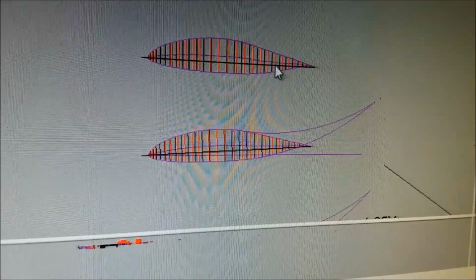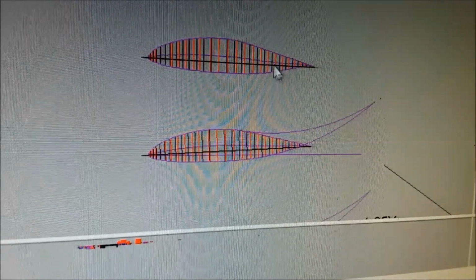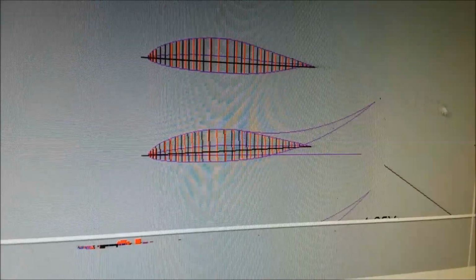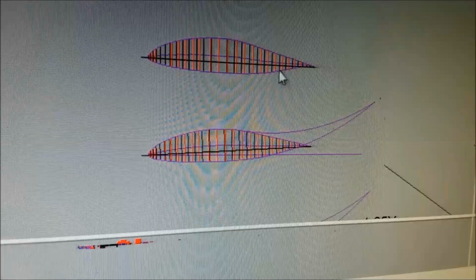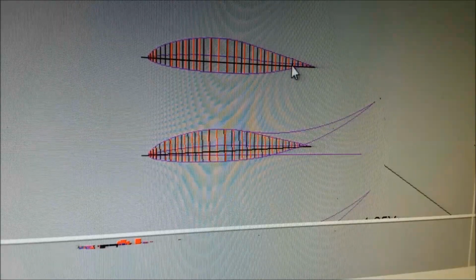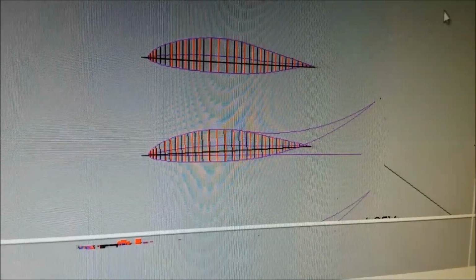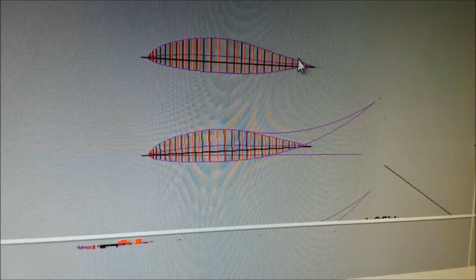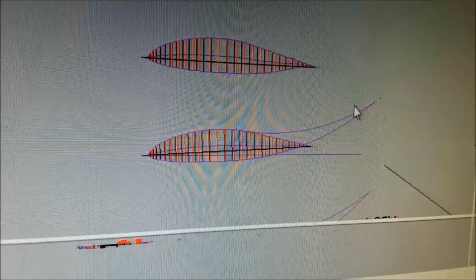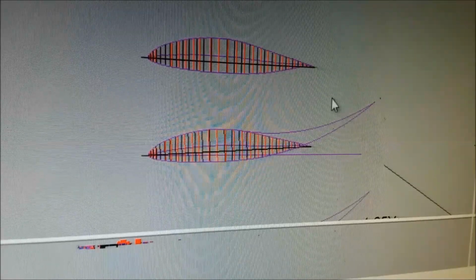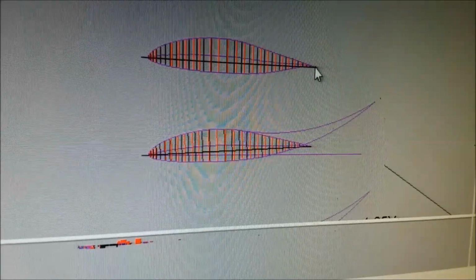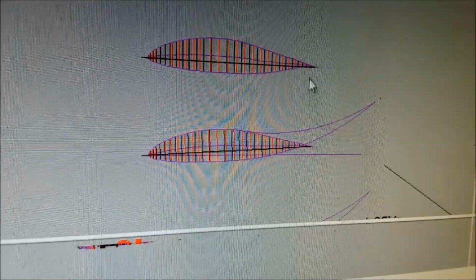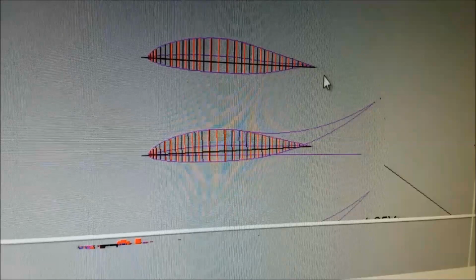If you have a Cessna Piper Cub kind of thing, the tailplane is down, but the wing is so high it never deflects the air down to it. But if you have a low wing plane, like jet airliners, most of the time you'll see the tailplane's up high on top of the tail. That's because of this air that's coming down. They have a lot of spoilers and devices back here that really send the air down. That's where most of your lift is, this air. You're putting a mass of air down, and the reaction against the air that's still coming is pushing the plane up.